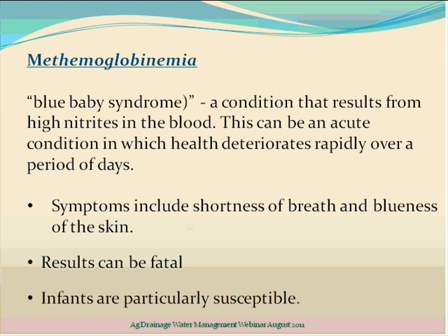It's a condition that results from high nitrates in the blood. This can be an acute condition in which health deteriorates rapidly over a period of days. The symptoms are shortness of breath and blueness of skin, and the results can be fatal. It especially affects infants. So we need to be really concerned about nitrates in our drinking water.